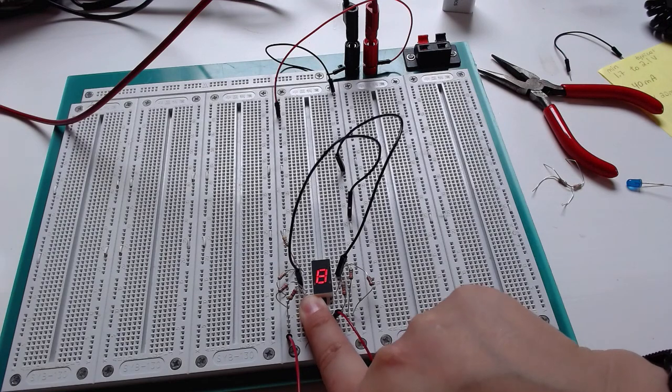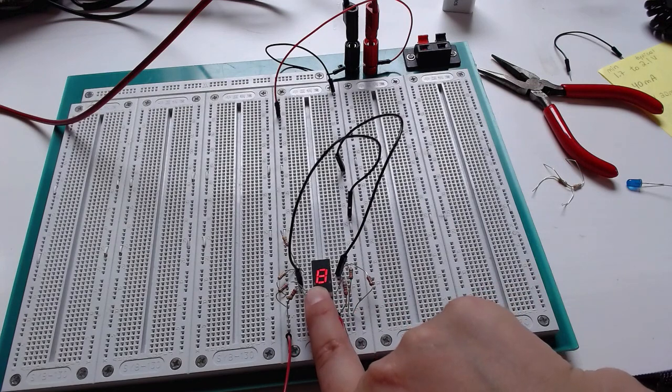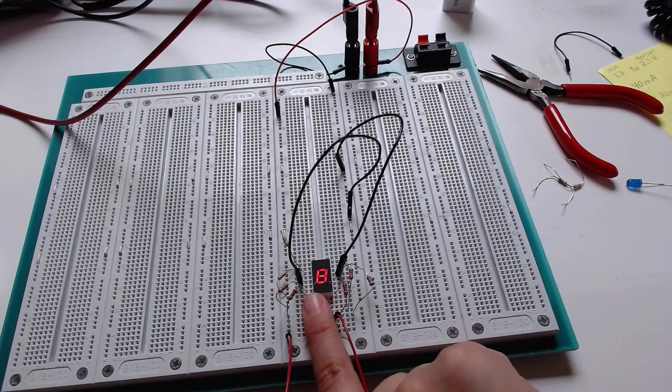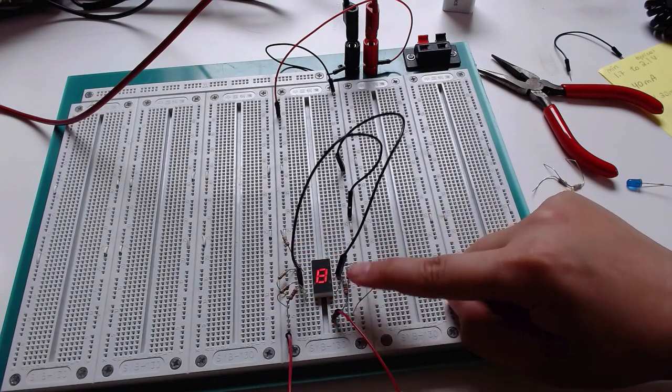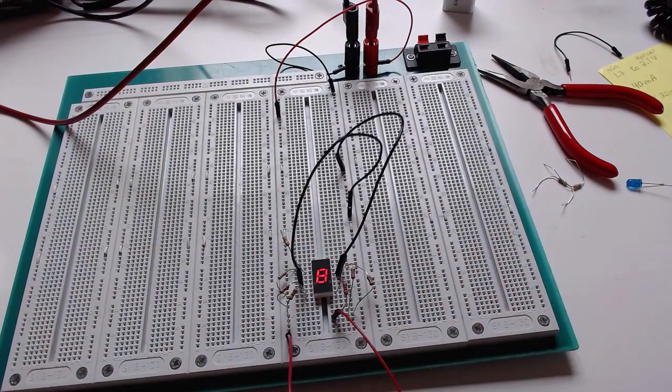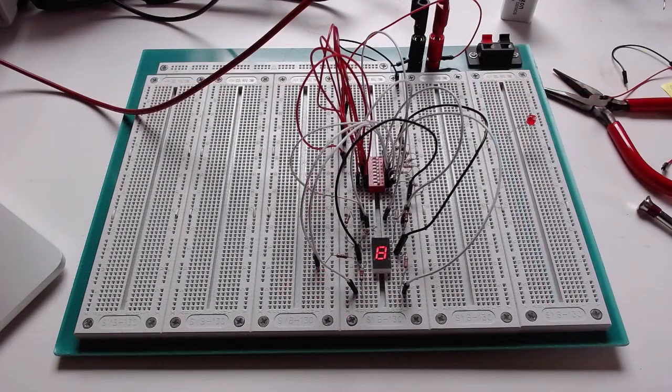So if I have a counter, for example, that I'm building out of digital logic chips, and the outputs of those counters go to a BCD to 7-segment decoder, then it's the outputs of my decoder chip that are going to be driving the display. Maybe I'm using an Arduino microcontroller, and the outputs of the Arduino pins are going to be driving this display. So very rarely are we ever going to have these resistors going directly to power. So let me hook up a dip switch so that we can use connections to our dip switch to turn each of these segments on and off.